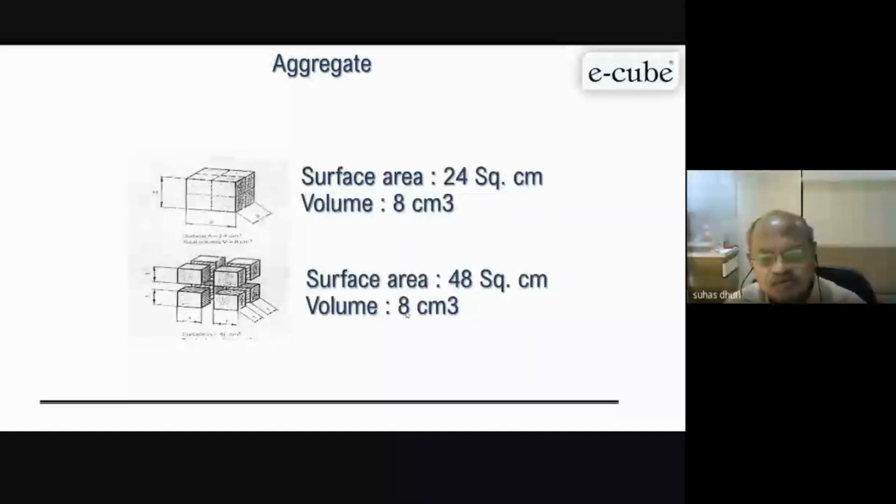So when you are taking by volume, this is the absolute volume. Your aggregate is the same, but surface area is more. Now, when you have a particular proportion of this material using a certain amount of cement content and water content, if you change this proportion, your water content will change, because your surface area is increased, it requires more water, more paste. This you have to remember in your mix design. Why we are insisting that whenever grading changes, you must change your water cement ratio. Water cement ratio keeps the same, but water content is changing, so your cement content will change.